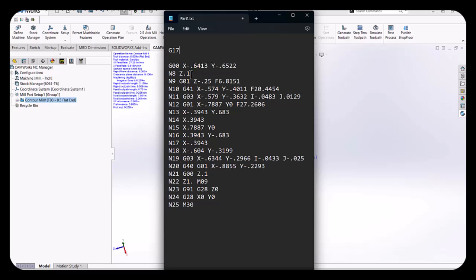At this point, we have a tool path that's basically going to go over our drop-in point. Then it's going to drop into minus 0.25 at a given feed rate. It's going to activate the cutter comp according to what tool our end mill is in. Then it's going to run around the hex down to your G0 Z.1, where it's going to come out of the hex after turning off the cutter comp. So everything past that point, we really don't need.